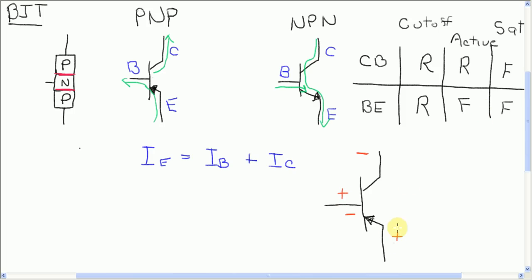In other words, current can now flow through here and have this reverse bias, and by changing this voltage on the base here, we can move it between cutoff and saturation, right? So once we get a bias set up, we have the ability to sort of vary the base current very slightly and have really big variations in collector-emitter current. That's called amplification, and there is a linear relationship, and we'll be talking about that more in future videos.